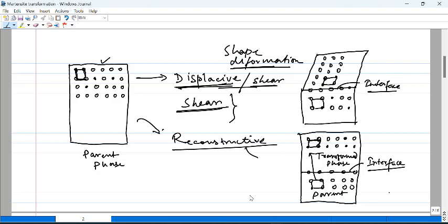Okay, we are cooling down the austenite phase to a temperature where it is not stable, right? So it has a driving force to change to another structure. And if it is cooled under certain conditions where ferrite cannot form, then the only other phase which could form is martensite. Okay, so the driving force here is different.